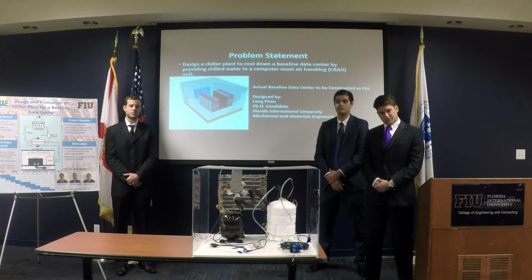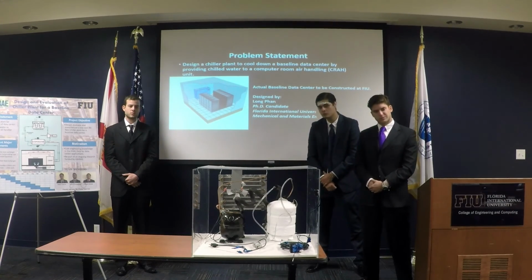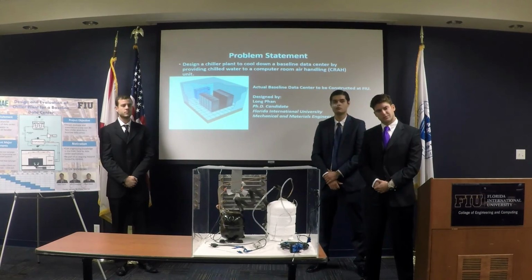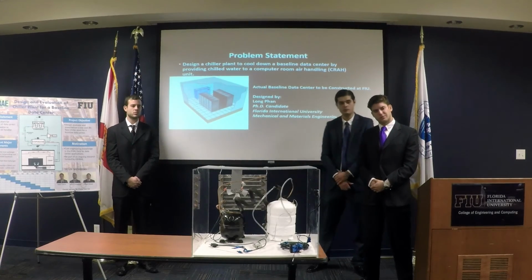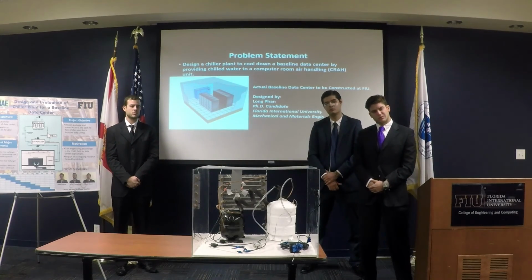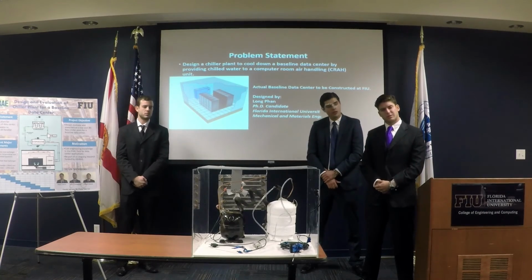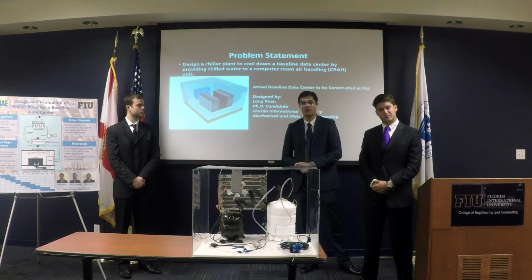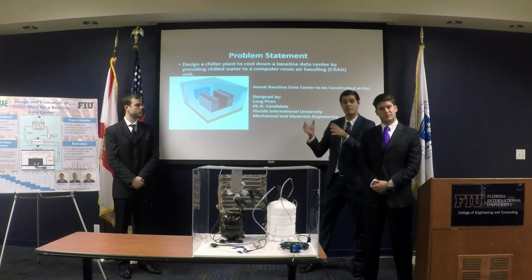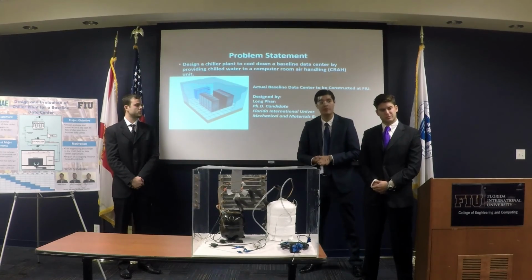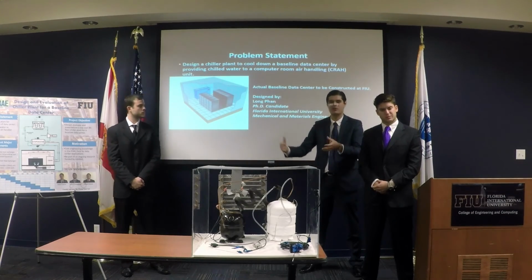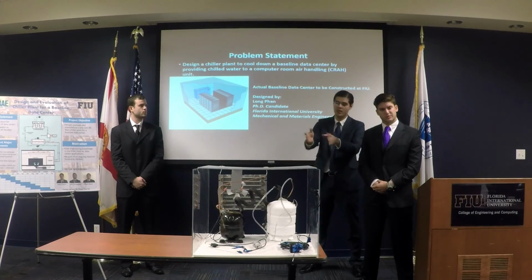As far as the proof of concept markup that you did, I see that you used 134A versus the 410 that you're actually doing in your simulation. What correlation did you get between your calculation simulations done on a 410 system versus your 134A? Can you speak to that? Well, for the full size scale, at the beginning we planned to use 134A, but we couldn't find compressors that were capable of providing the capacity using that refrigerant. So by using 410, which is a high pressure refrigerant, we were able to have those capacities. Now for this small design, 134A was the way to go.